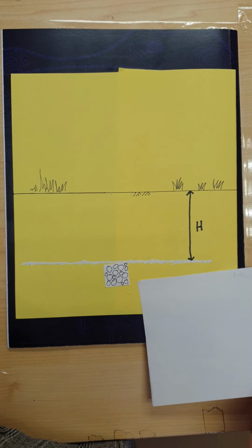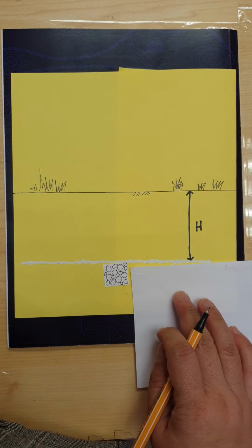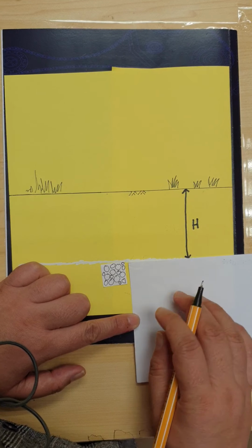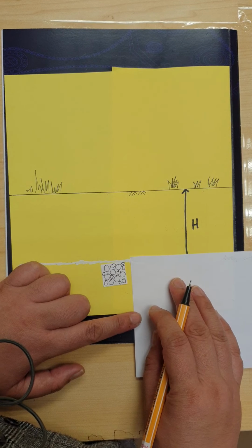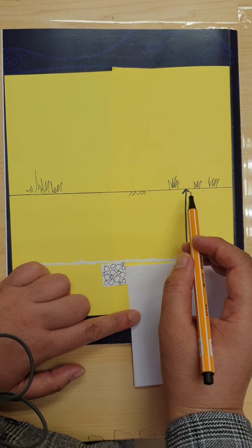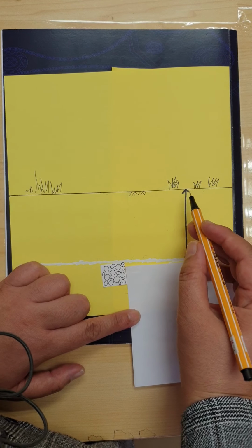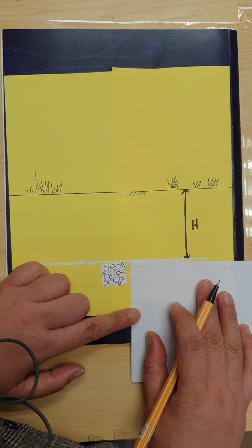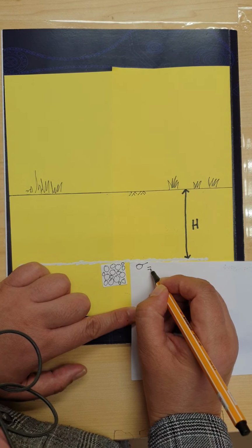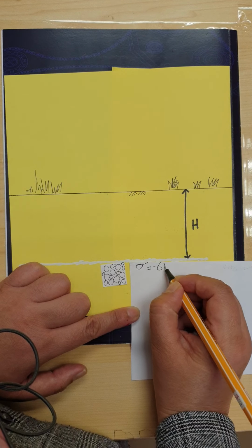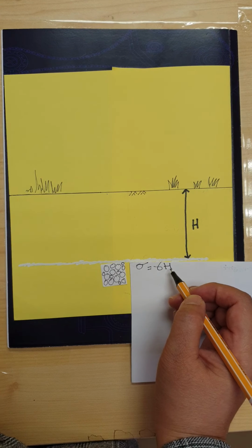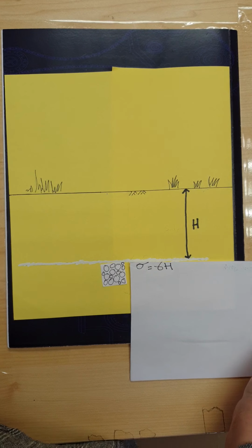In this scenario, you have a point and you don't have anything else. Because we have gamma, the stress at the point comes from this height to this height, from the ground to this point, and that will be H. So what that point will experience is stress equal to gamma H. Gamma is the unit weight of the soil as mentioned earlier, and H is the height of the soil.